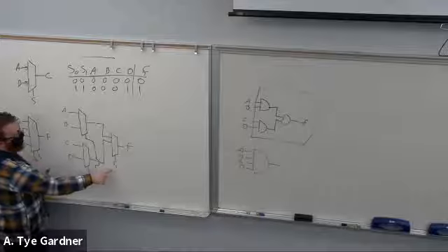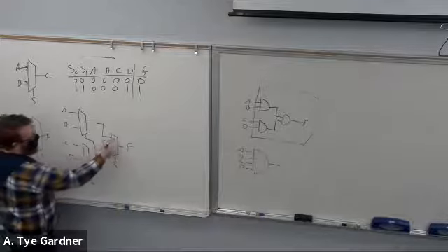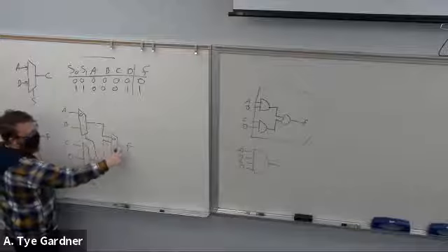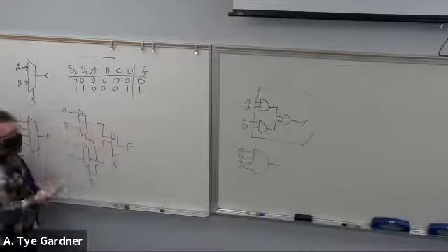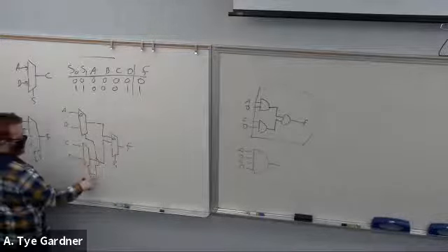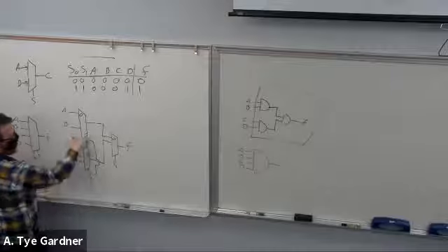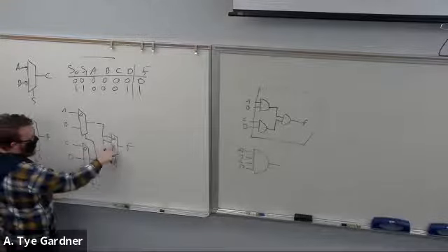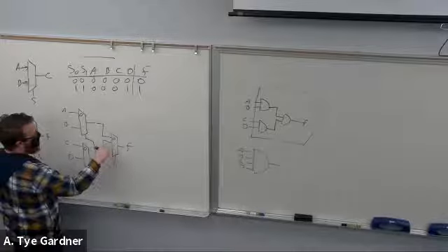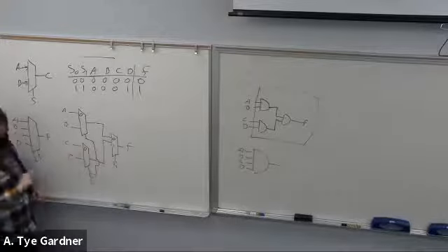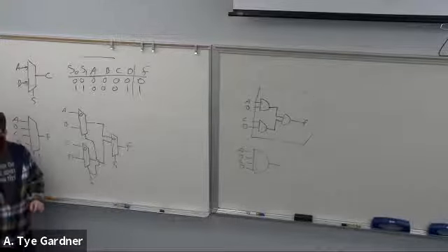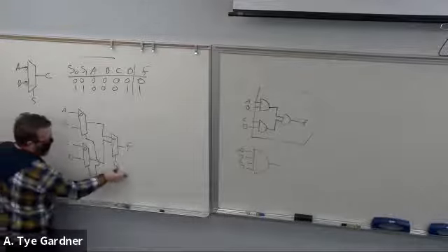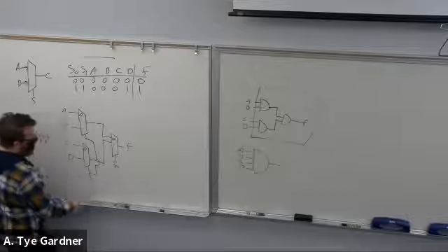So if I set 0, 0, then I'm going to get 0 here, right? 0, 0. A flows to here, A flows to F, F is equal to A, perfect. 0, 1, both of these are on 0, so I have A or C, and then 1. Well, then I have the issue that actually 0, 1 becomes C. So don't feel bad, I actually made this mistake in my last class when I did it. So we actually want to flip them around to S0, S1.